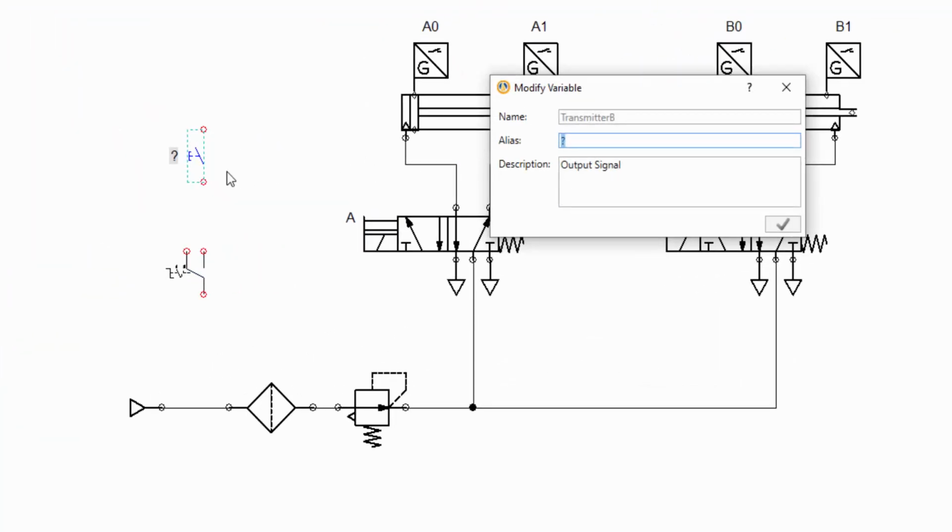When inserting an electrical control component on the schematic, the software asks for an alias for the component, which is displayed on the schematic and is used to identify the component by linking it with other components. Let's give it an alias on/off and apply.